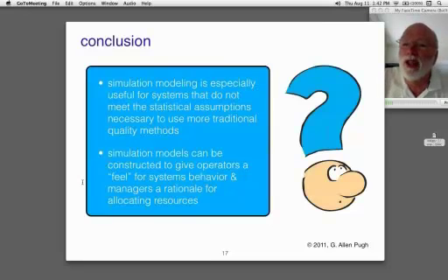Michael, Steve, what is the difference of small lot that Dr. Pugh mentioned under the definition of small lot? Actually, by small lot, I mean lots in a more technical way in which the hypergeometric distribution has not yet decayed to the binomial distribution. I'm sure that horrible mouthful sounded pretty gruesome. What it really means in the end is that if you're starting to get lots that are smaller than 50, and especially smaller than 30, you have a small lot. That's a nice easy rule of thumb to go by.